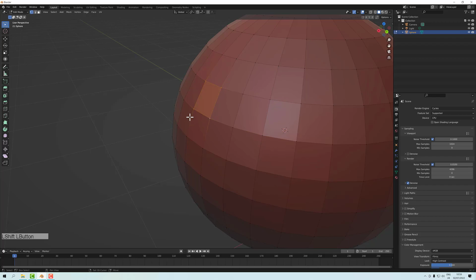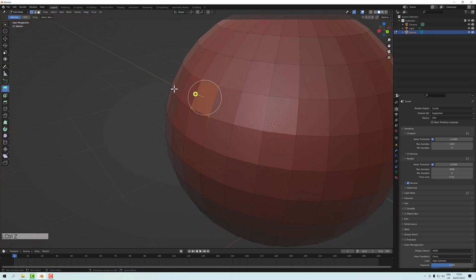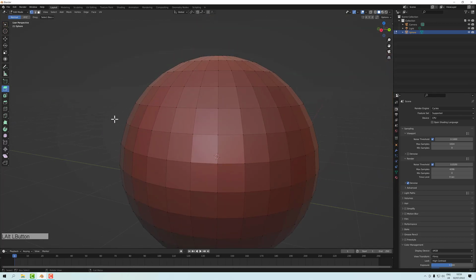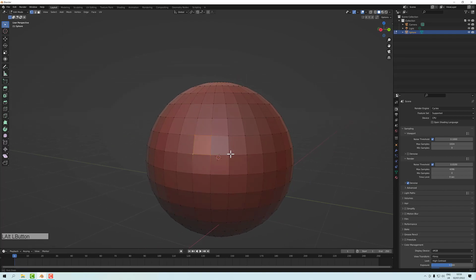If I'm in vertex mode and I do an extrude, so extrude region, it will act on the polygon that I have selected, even though I'm really in vertex mode. Okay, so let me undo that. There we go. So you can select and then press shift to select other things. Let me switch that back to selection, and that's all well and good.